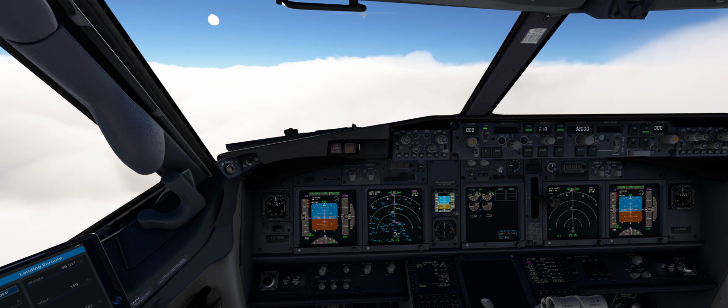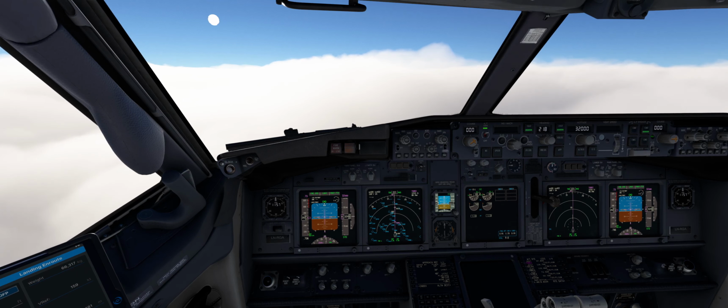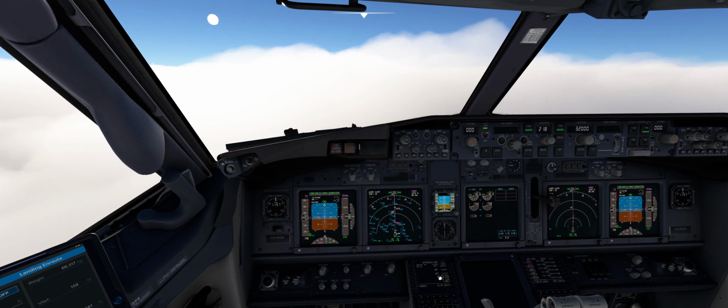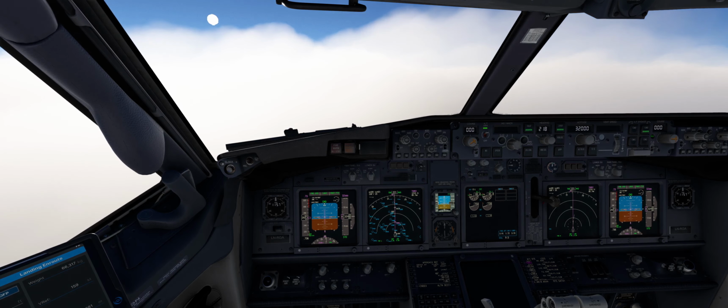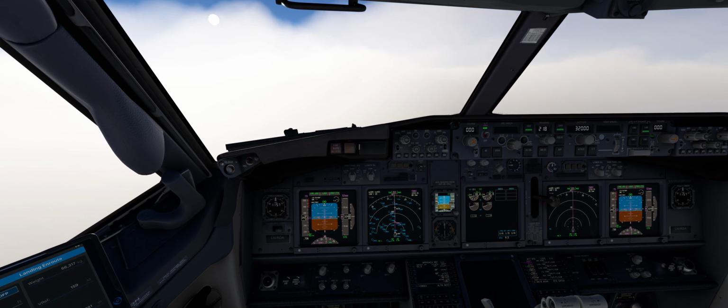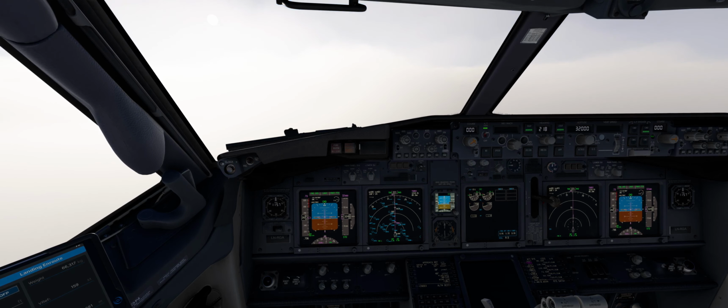If the wind condition is, for example, we have strong crosswind or gusty conditions, I will go for flaps 30. If there is still air conditions, we can use flaps 40 if the runway is too short. So that's the basic explanation for the common sense what auto brakes and what reversers I am using.